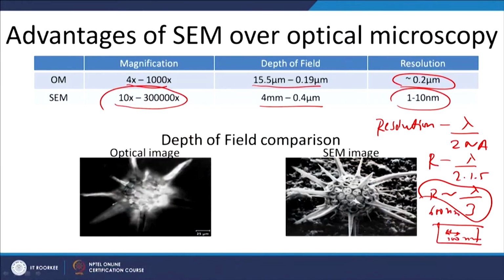So, obviously by using this optical microscope I will not be able to get a good image of these perovskite grains, but if we use a scanning electron microscope, then I can know what my grain size is, what the composition in the grain is. I can even do grain engineering, or morphology optimization to find out the proper morphology, so that the photophysics is also supported. So, that is the importance of the SEM in solar photovoltaics.